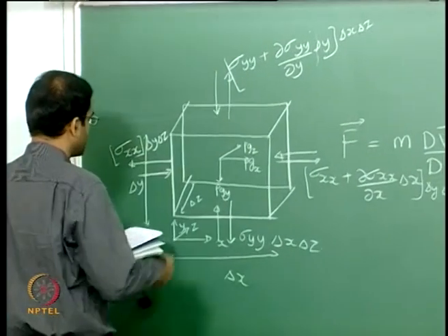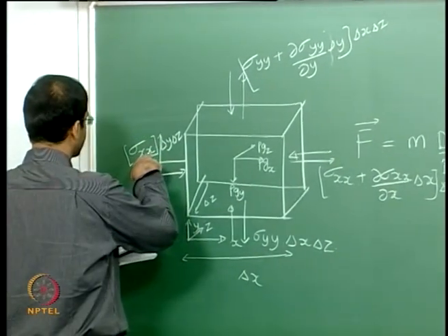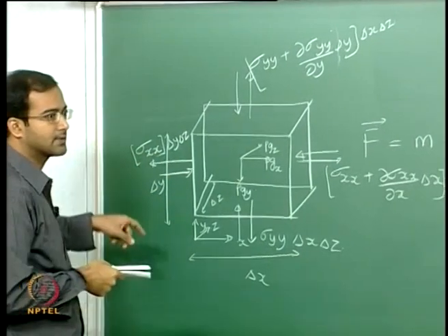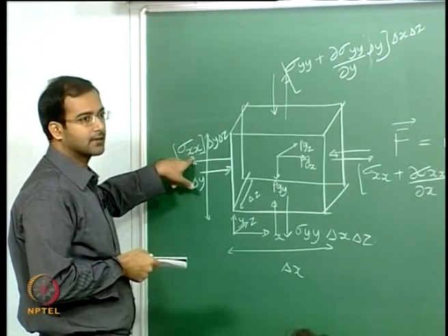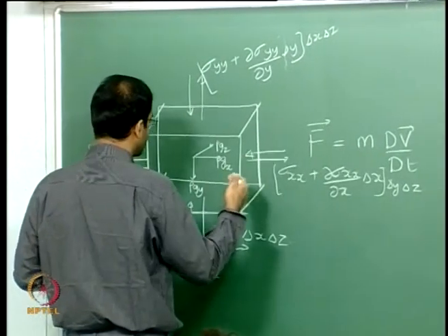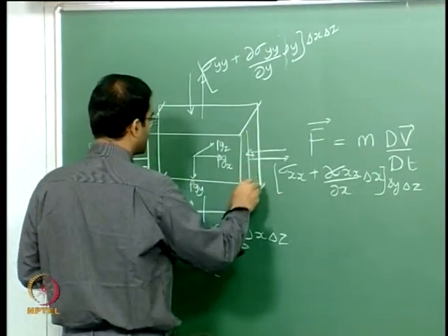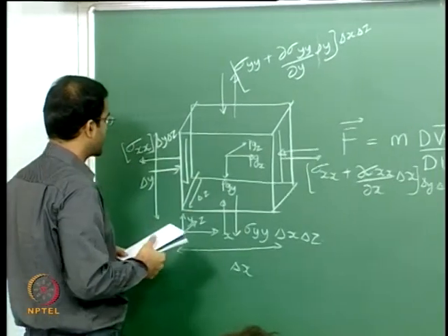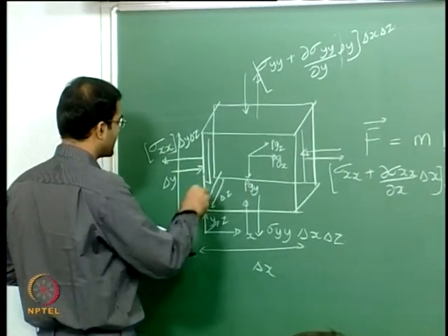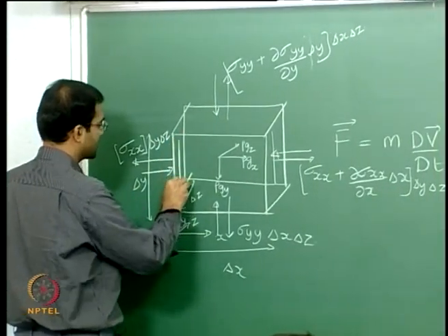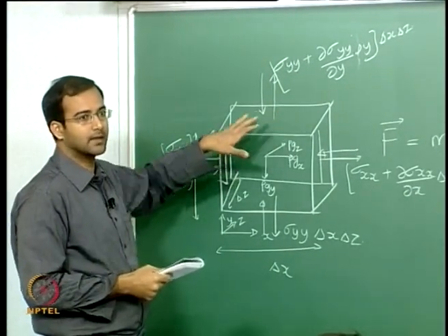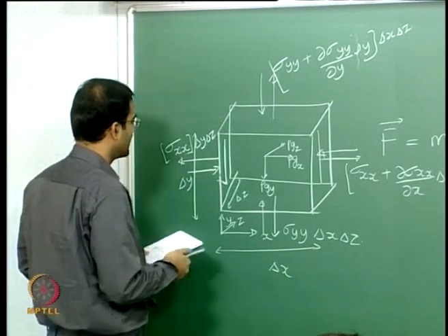Now if you look at the notation, the second index, the last index, corresponds to the direction in which the force is acting, and the first index denotes the plane on which the force is acting. So if you want to, for example, calculate the shear stress acting tangential to this x plane on the left side, let me say that this force is acting in the downward direction. You can also say the force is acting in the upward direction and you will get the same result, but in our case we will say that this is acting in the downward direction. So this will be tau.